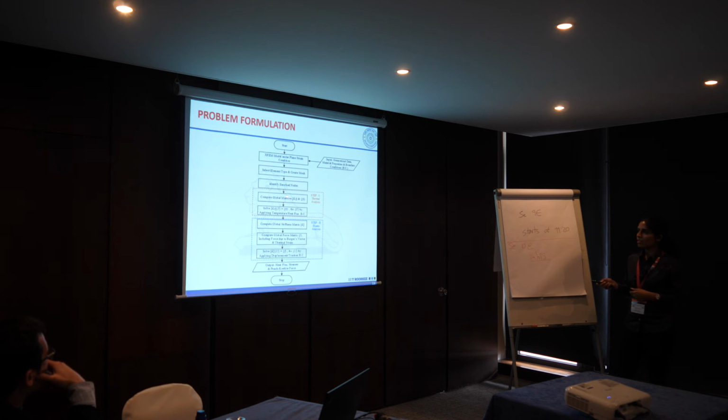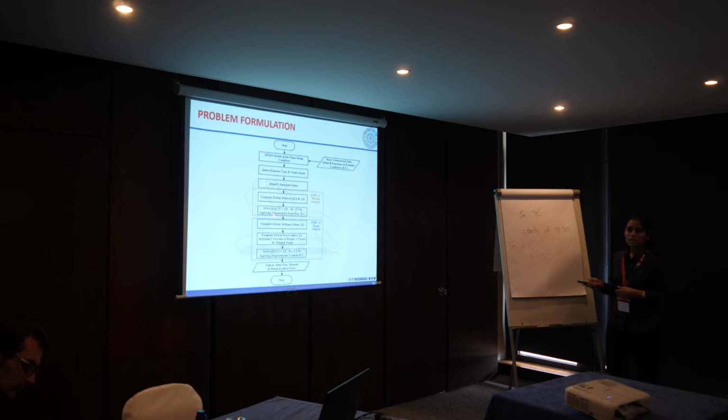Considering the modified shape functions, the global matrices are obtained as K_T and F_T, which will be solved by applying the temperature and heat flux boundary conditions. We will get the solution for the thermal field. Considering these thermal strains, we will then calculate the forces in the displacement field. For that we will calculate the global stiffness matrix for the elastic case.